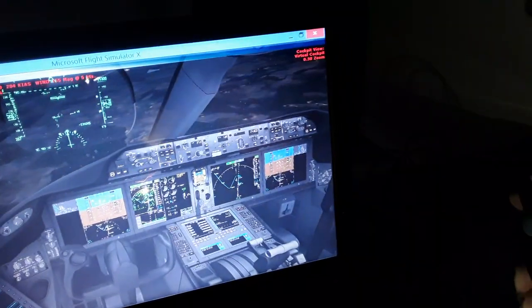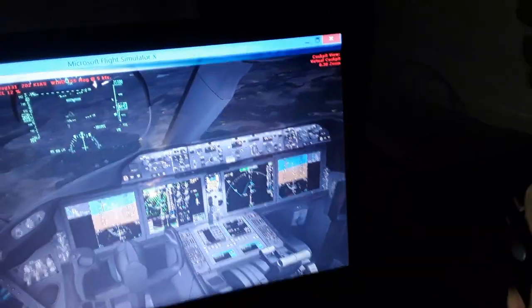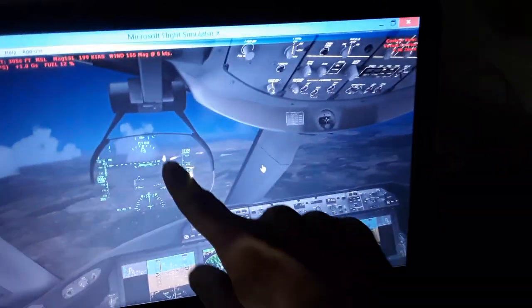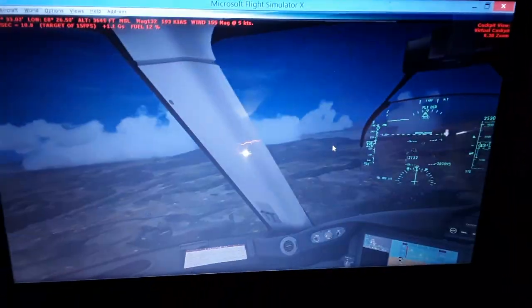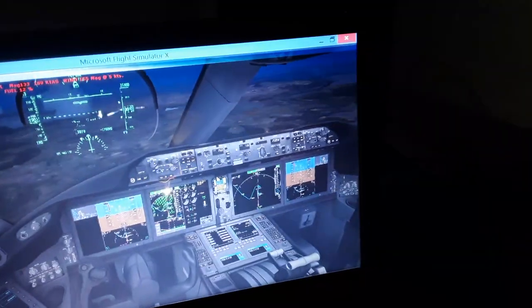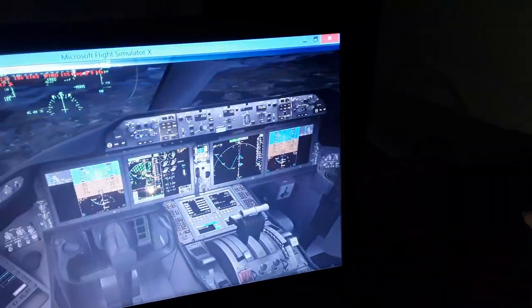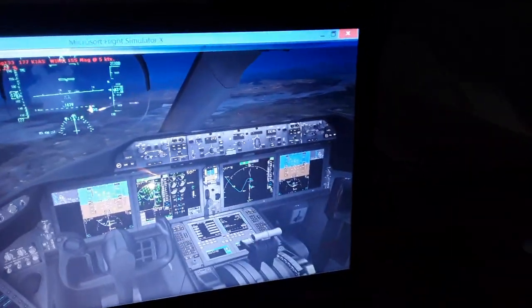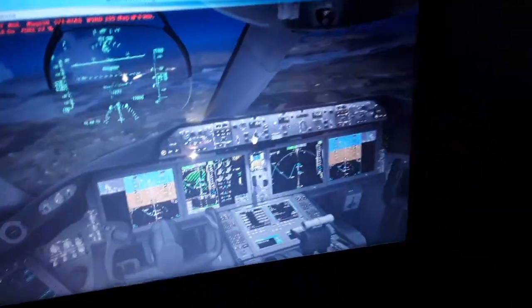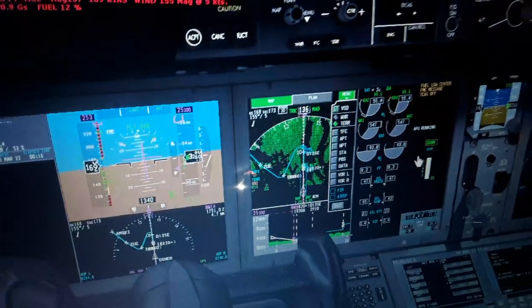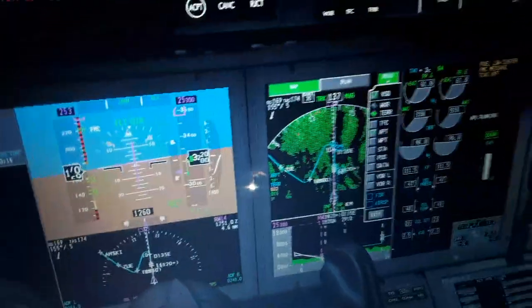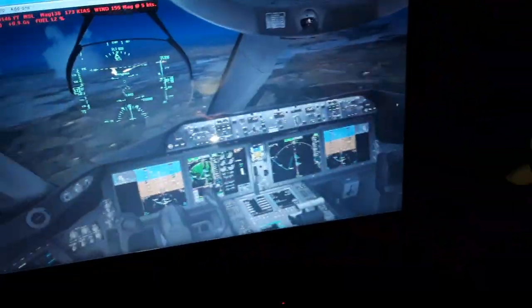So we are approaching the runway. Use full flaps, idle thrust. Also you can see the runway displayed here. Use a little bit more thrust over here for approach, and flaps also, more flaps. So we align with the runway heading. We have also the LSZH localizer over here. You can see the LSZH localizer information as we are approaching the airport, the runway.